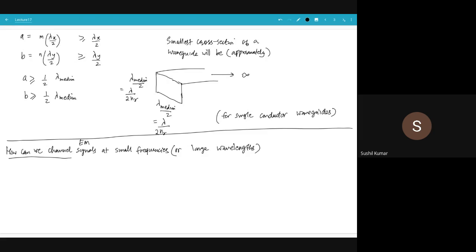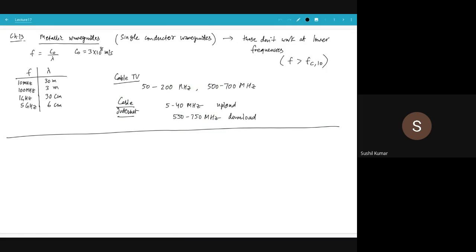So let's say you are doing an AC signal in your circuit. Let's pick an example, just so you have some realistic number in mind. Instead of 10 megahertz, 10 kilohertz. For 10 kilohertz, what will be the wavelength? Shan, what will be the wavelength for 10 kilohertz if you just look at that table and not calculate? 30 kilometers? Yes, exactly. 30-kilometer wavelength.